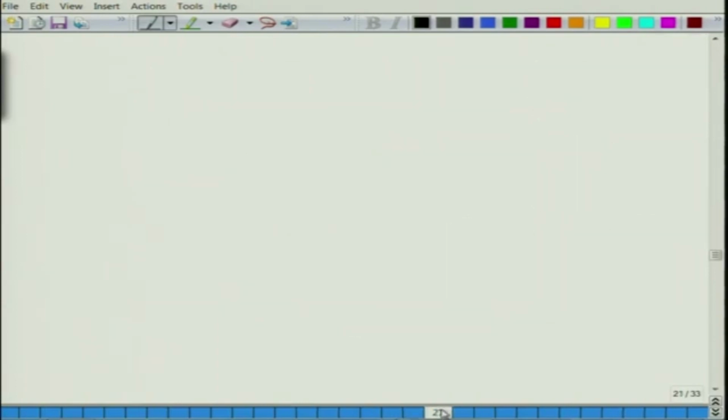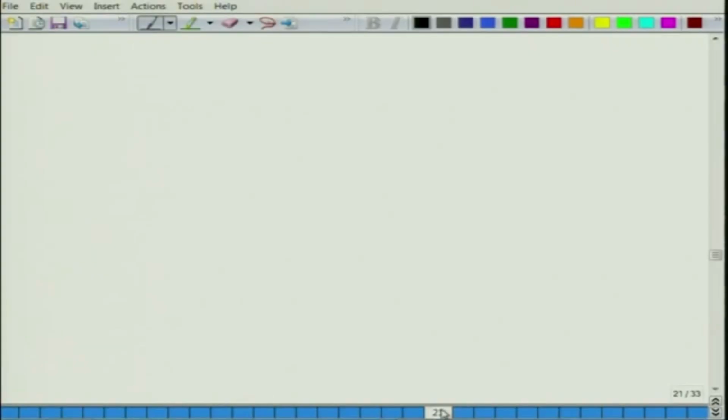Now, if these are the view factors, the expression that we have written will be simplified in terms of the isotropic sky, as we put these view factors into the expression. We get this particular expression where the beam part is unaffected because we did not make any changes to that. For the diffuse part, we have now gotten rid of all the different diffuse parts like isotropic, circumsolar or horizon brightening.